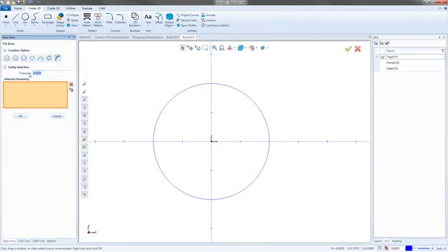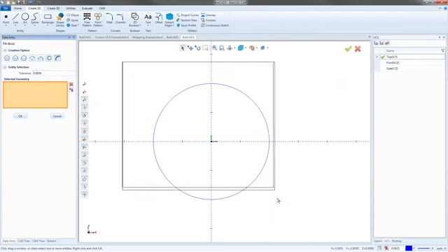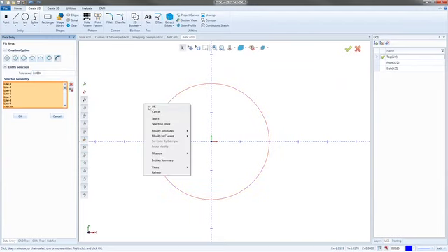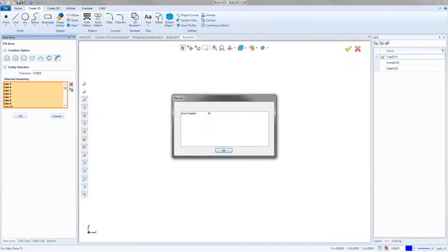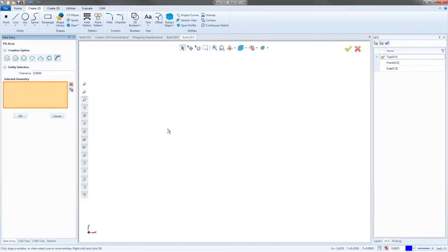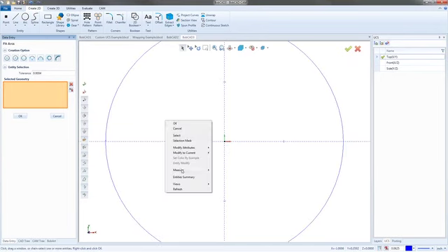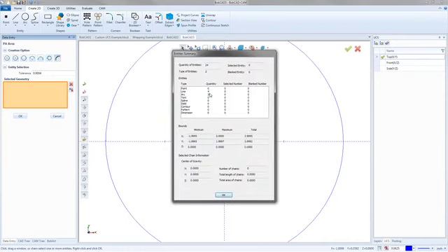By default, the tolerance is always going to pop up at 4/10. If I drag a box over my part right now and right click and hit OK, all I'm trying to do is rebuild this arc. It was 141 line segments before. I want it to be a lot less than that. So we'll see right now we went down from 141. We still have 4 lines on there somewhere, but we have 20 arcs. So it's getting cleaner. It's just not as clean as we'd want.